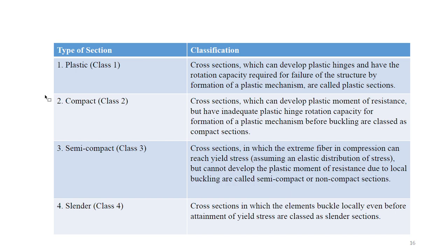The failure at those particular 2 joints, in case of fixed support conditions: if the beam fails at any 2 locations in that particular beam, meaning if it breaks at any 2 locations, the section is not going to take any moment at those locations. And if you keep any body on it, the section won't withstand. It keeps on moving in the downward direction, or the upward load applied direction. It will break at a particular point. Those types of sections we used to call plastic sections.